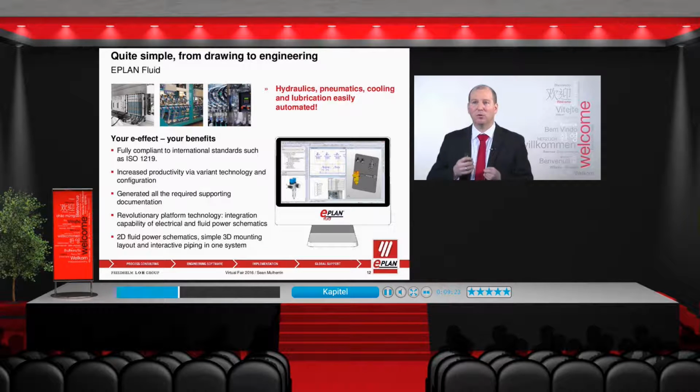EPLAN Fluid also provides the ability to lay out your enclosure in 3D. So you can lay out your components on a panel and also do all of the tubing as well as the piping within that particular panel. So you have a full, complete documentation for your fluid power system.